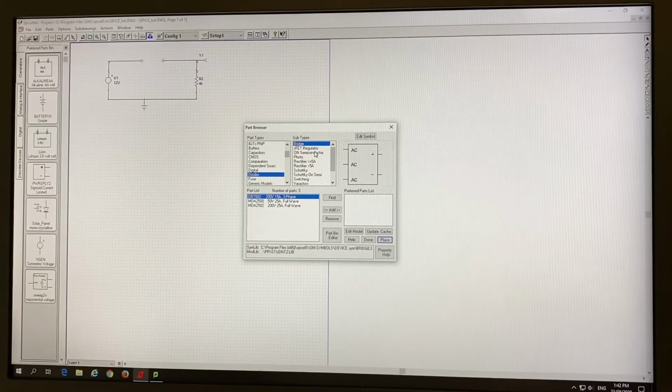Then, as you can see, there are many diodes. There are bridge diodes, junction FET, transistor regulator diodes, there are photodiodes, mostly used in car lights. There's the Shockley diode, there's the Zener diodes. We just want a switching diode, just a small switch. It works like a switch if you want. Just this, then exactly what you want, the 1N4148 diode.